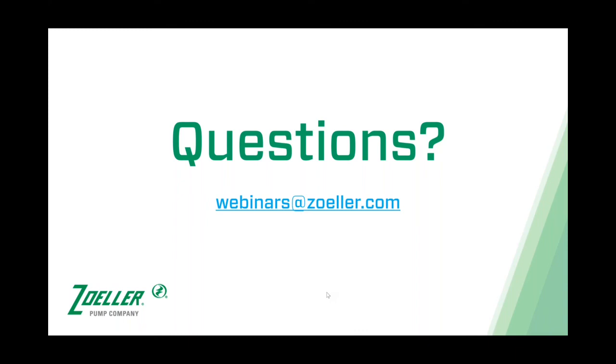That's number one. But let's say they didn't do that and power does go out and the router goes down. So worst case scenario, there's just no more communication. Remember we talked about the heartbeat. Every one of our devices out there is checking in with our cloud every 30 seconds and updating the cloud. When our cloud doesn't see that heartbeat for 10 minutes, notifications to all users, all recipients go out. So whatever happened to knock out communication, including a power outage, in 10 minutes they will get a notification saying that their device has lost communication. So that's kind of the fail-safe.